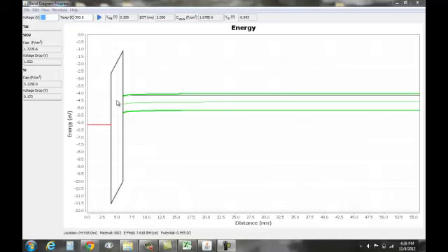I would click on this point, which will turn the bottom panel text and numbers from black to blue. The blue means that it's frozen, so I can move my cursor down there, select the number, and press Control C to copy it. I can unfreeze that panel by hitting Escape, and it will change from blue back to black.